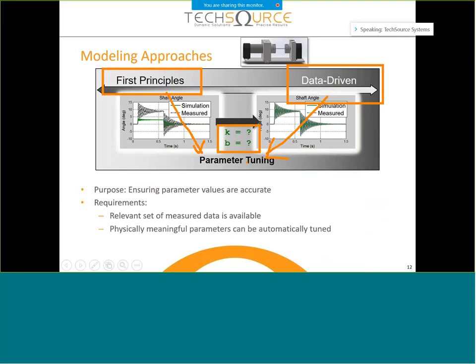For example, if you're modeling a part of the system, let's say a motor, it's easy for you to get from the spec what the coefficient, what the friction is, etc. But in the real world, there are friction, viscous forces, and other types of more difficult parameters to tune. Then we use parameter tuning to tune our plant.